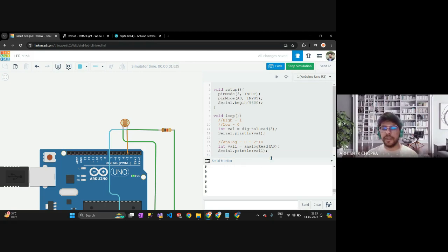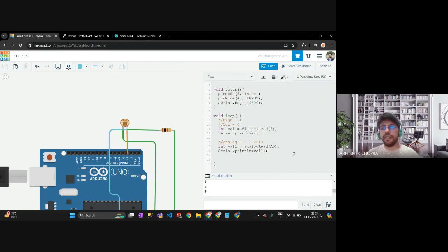So we'll make this a bit pretty. What we can do is give a print. I have to stop the simulation. I'll give it as print. What print does is print whatever text or value you have given here. It will print all of it in a line. Similarly, the println, as the name suggests, will go to the new line. This function will go to the new line and then print this value. So what we're trying to do is make this a bit more readable, not fancy.